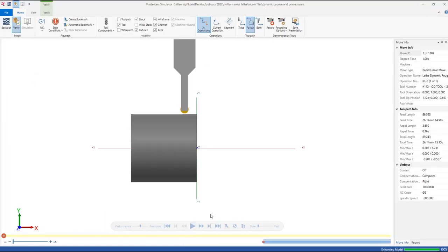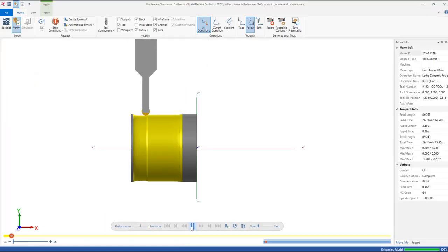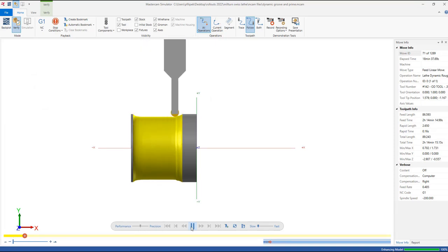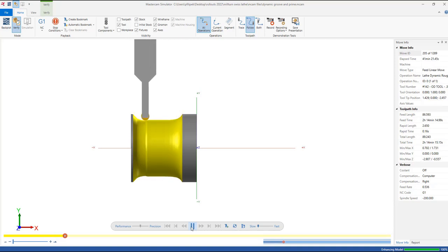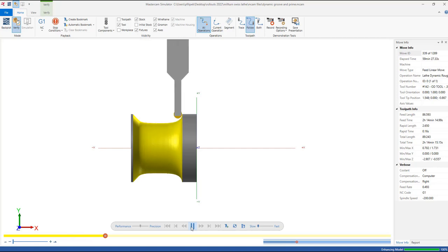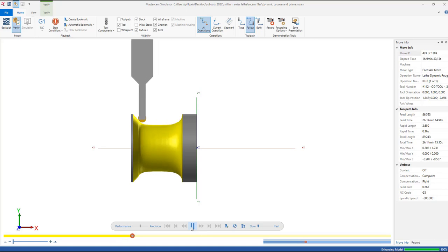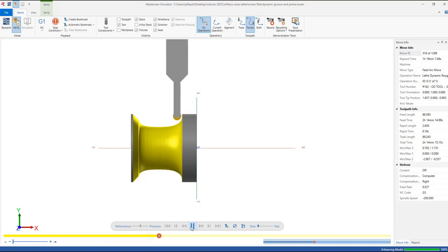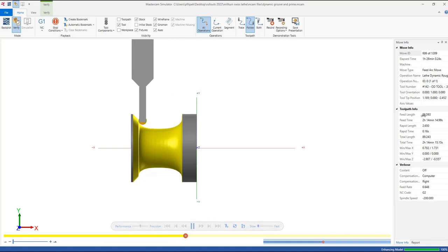Now if we go ahead and look at this and verify, this is a very nice toolpath to look at. As you can see, it scoops it out. So there is no plunging, there is no stabbing with the groove tool that can create some issues. This is just nice fluid motion, maintaining the chip all the way through. So that's a great and valuable toolpath that I just don't see used, because I think a lot of people are just kind of hanging out with the old stabbing style tool path, and that's what they're going with, but this can greatly reduce cycle time for you.